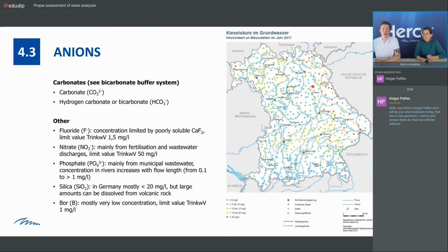And previously, in the past, they did systems where they recirculated a lot of concentrates and EDI concentrates and put it back in the front in the unit. And this is where they concentrated also these silicates, and they scaled everything on the EDI systems. And they wondered why an EDI system only was working for 3 years. And this is just some basic knowledge that they grew over the years.